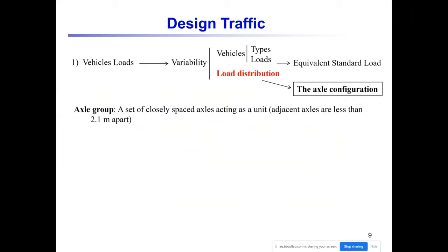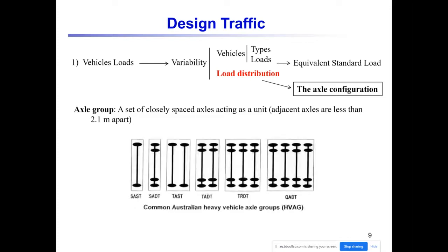The other one, as I showed you, depends on the load distribution, how you transfer the load to the pavement. So this load distribution depends on the type of the axles or axle groups of the heavy vehicles. Here you can see different types of axles and axle groups.